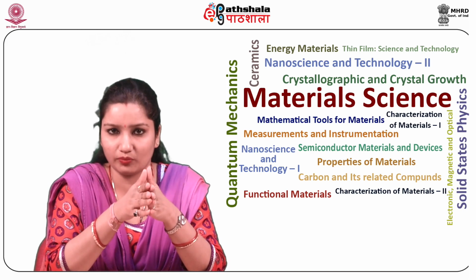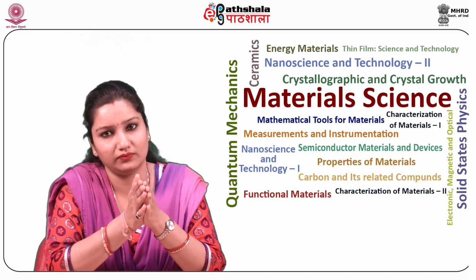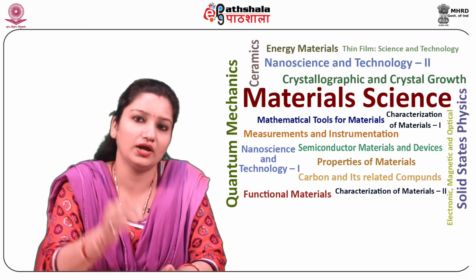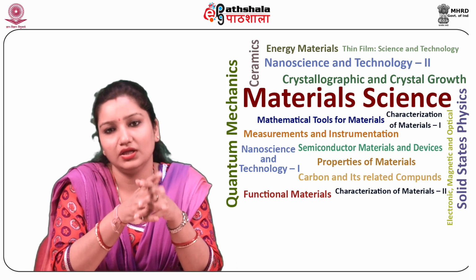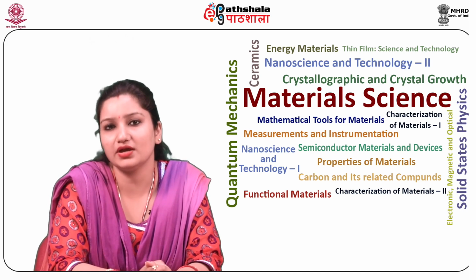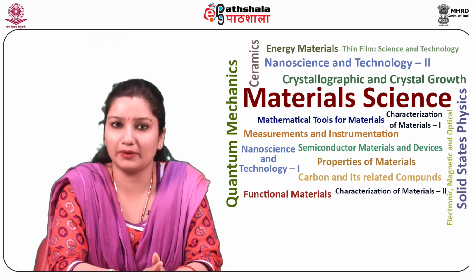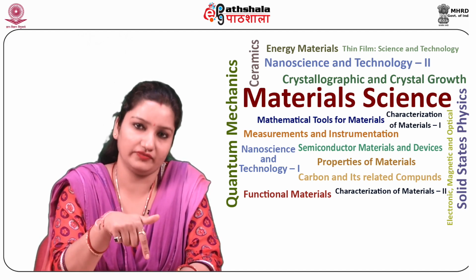This etching is isotropic and thus can lead to damage of the pattern below the photoresist also. So, anisotropic etching can be used as a substitute in which directionality is induced into the etch process. In this case, if wet etching does not serve the purpose, then dry etching or plasma etching comes into the picture. In plasma etching, the etchant is replaced using plasma, that is an ionized gas. An electric field is applied that causes the ions to be accelerated downwards towards the wafer.